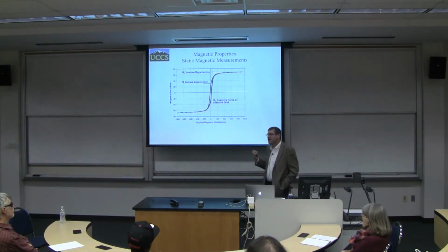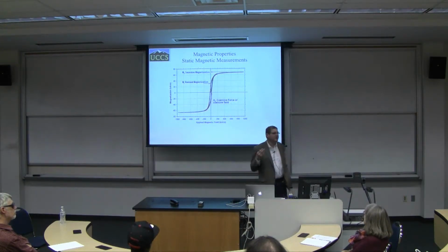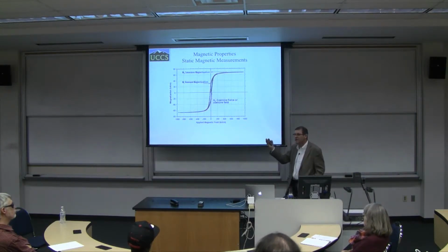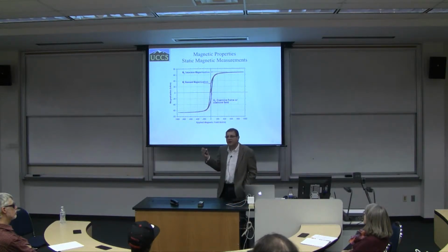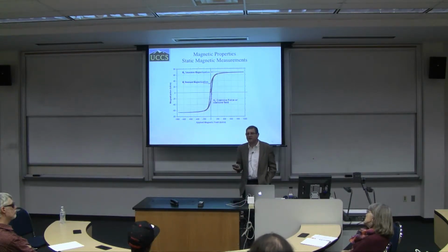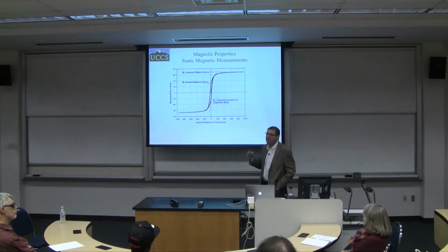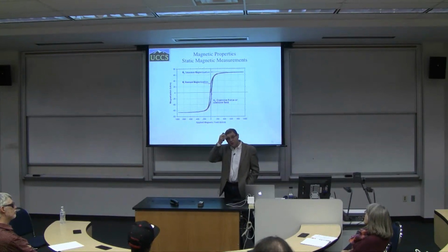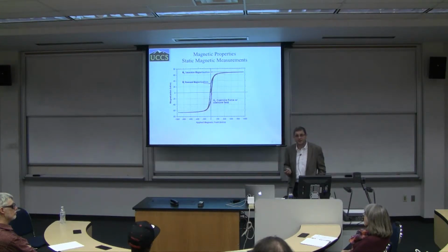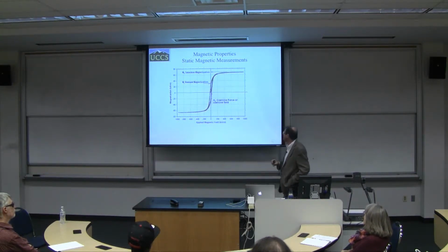This is extremely important if you think about it, because how do you get electricity to your house? Somewhere there is a generator which makes electricity, but then it has to be sent to your house. Typically it's sent maybe at 110 kilovolts, then comes down in the city to 25 kilovolts, maybe then 10, 5, but eventually in your neighborhood you have 480 volt lines, which then come down again using a transformer to 220 and 110. Actually 208, let's say, because 110 is just two different taps in 3 phases.